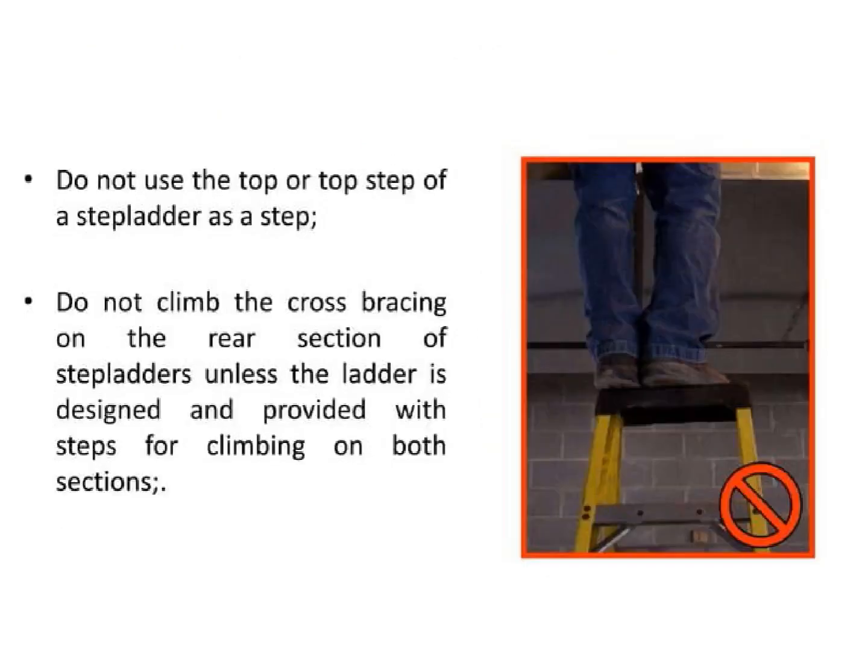As you use stepladders, make sure that you do not use the top or top step of the ladder as a step. It is not designed to support a weight and could lead to a fall. Additionally, make sure you do not climb the cross bracing on the rear section of stepladders unless the ladder is designed and provided with steps for climbing on both sections. This is important for your safety and can help prevent a fall.